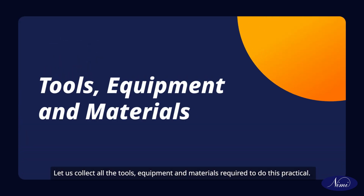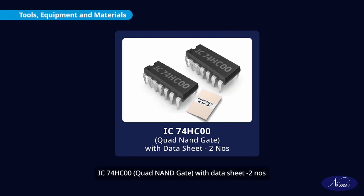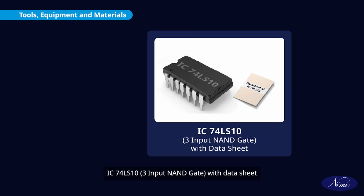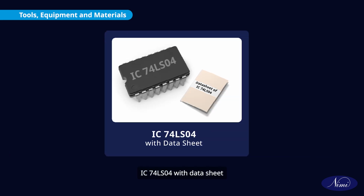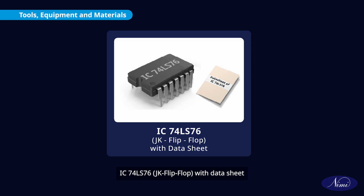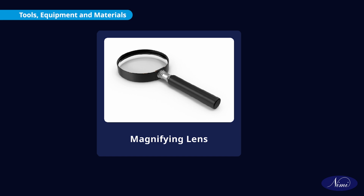Let us collect all the tools, equipment and materials required to do this practical. Digital trainer kit with user manual, IC74HC00 quad NAND gate with datasheet, 2 numbers, IC74LS10 3 input NAND gate with datasheet, IC74LS04 with datasheet, IC74LS76 JK flip-flop with datasheet, male-to-male jumper wires, magnifying lens.